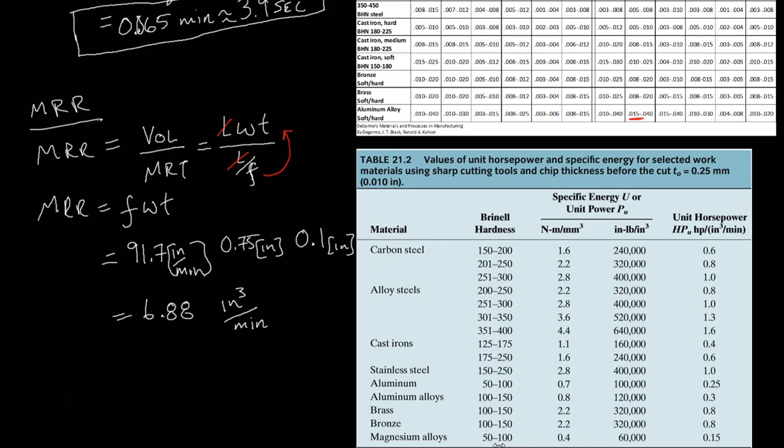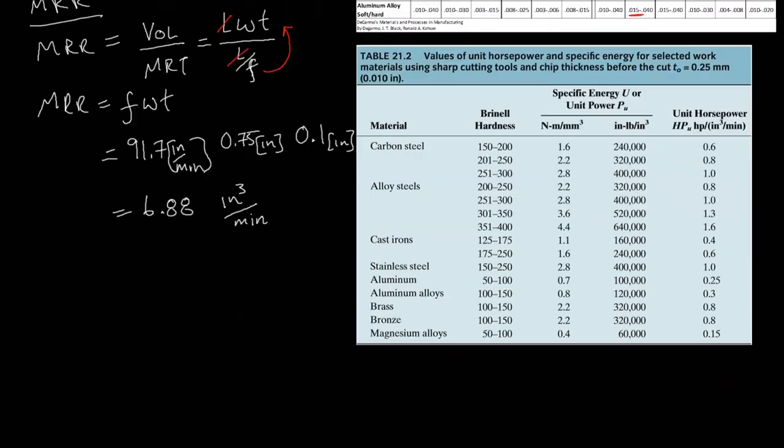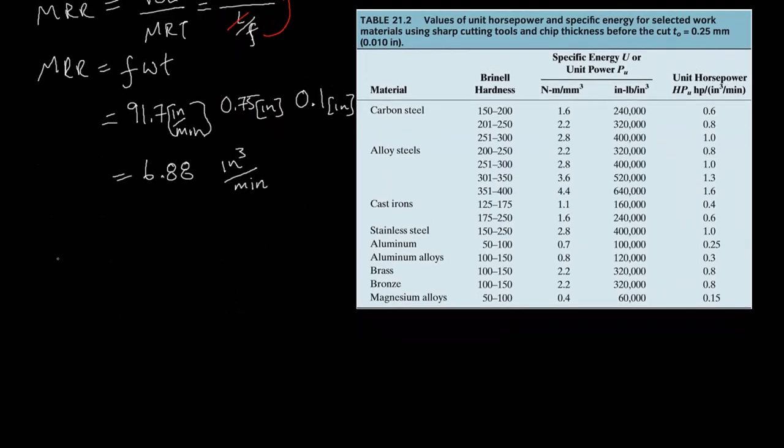So now that we have our material removal rate, we can calculate our power. So how much power, what size of motor, and what sort of power supply do you need to feed this machine? So power is equal to our unit power times our MRR.